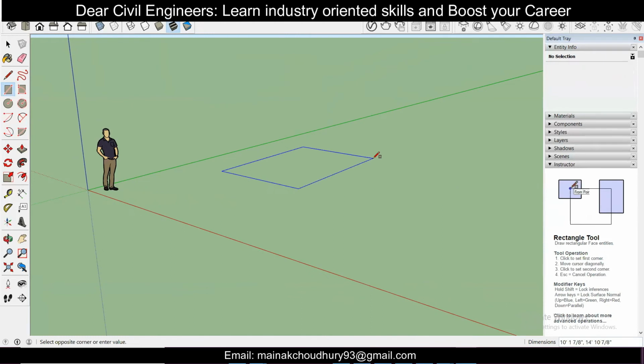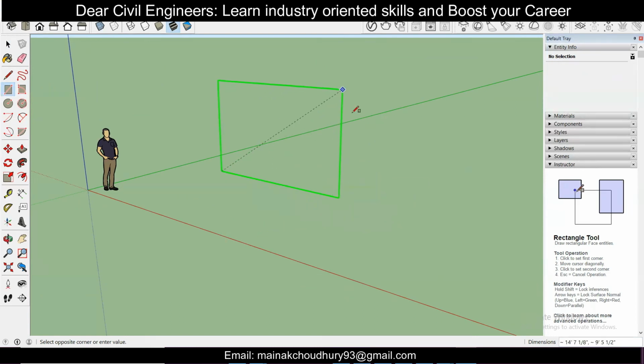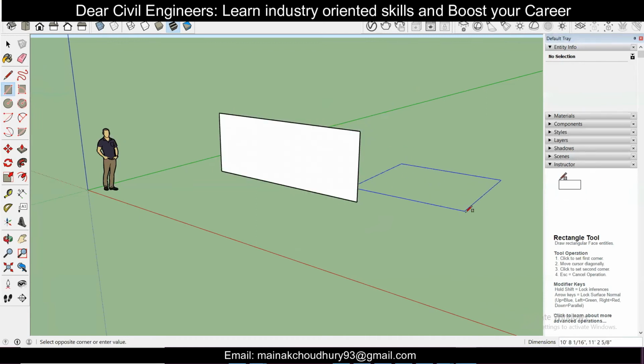If you want to draw on the red axis, just click on this right side arrow, and we'll be drawing on the red axis, and the left side arrow will be drawing along the green axis here. So it is pretty simple here. Just drawing a rectangle here, and like this along all the axes you can draw your rectangles.